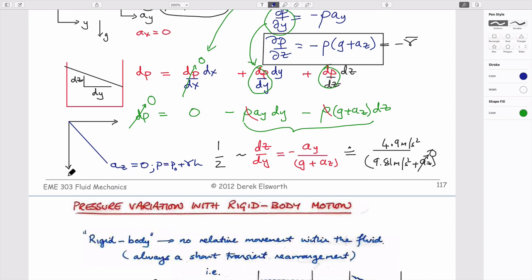And I should label these, right? This is minus Z. This is positive pressure. This, I suppose, is plus Z. Remember that our sign convention is always, and we'll have to be a bit more rigorous about that now when we move into Bernoulli, that z is always positive upwards. I wrote it in terms of h just because it's convenient to do that.